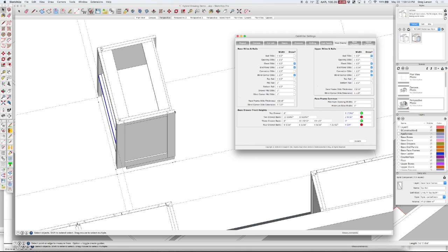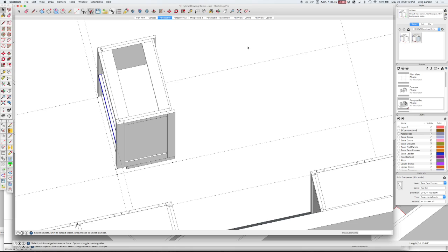And also, if I'm going to start drawing my cabinet right here, if I draw that as a frameless style on this end, it's going to bring the drawer and door all the way over to this point, and I don't want that. So what I'm going to do is just leave all this as is, and I'm going to override my butt style when we get there. You'll see what I mean here in a sec.